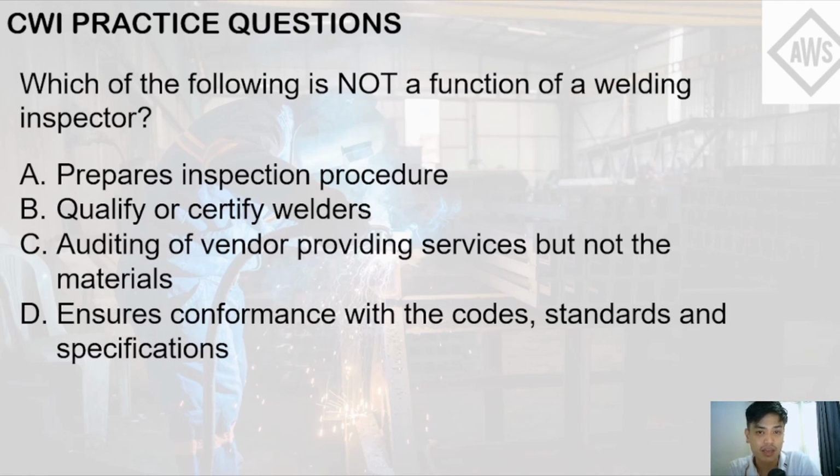The documents like MTRs, mill certificates, the factory standards used for the production of the base metal, and the destructive testing used prior to shipment should also be analyzed and scrutinized by the welding inspector.